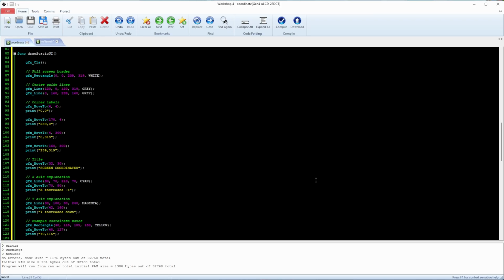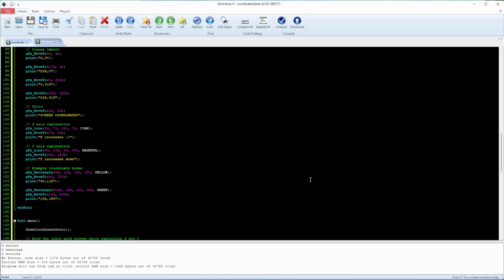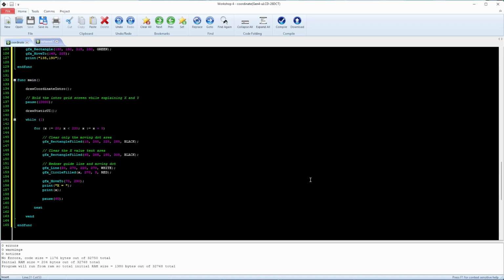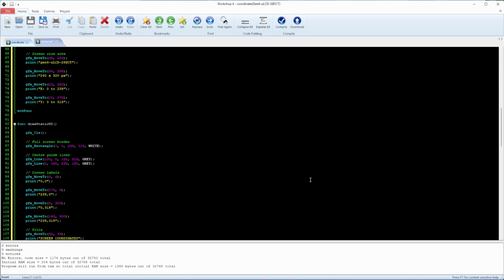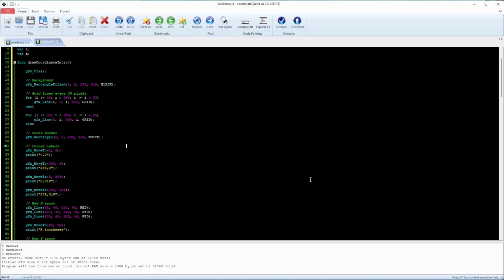This is a good habit to get into because if you clear the whole screen every time something changes, the display can become flickery or messy. But if only one section is changing, you can usually just clear that section and redraw it. This same coordinate logic applies to touch as well. When you read touch input from the display, you're also working with X and Y values.